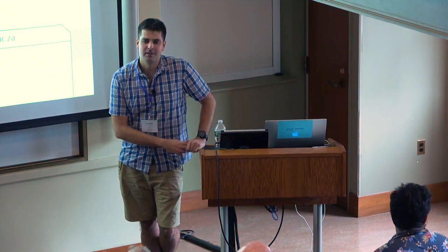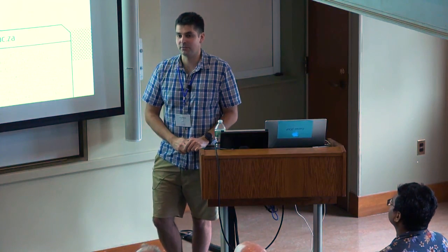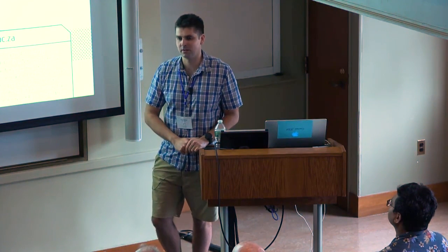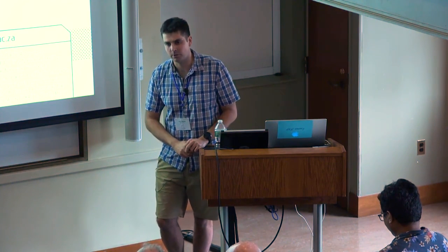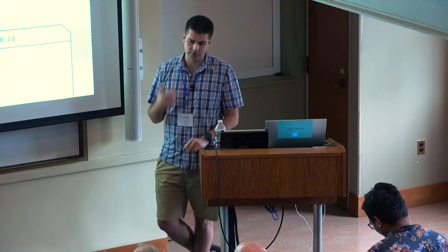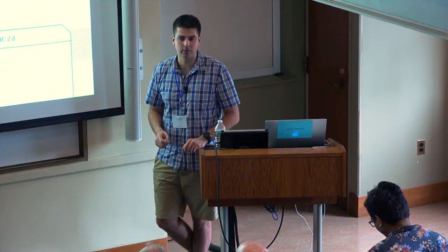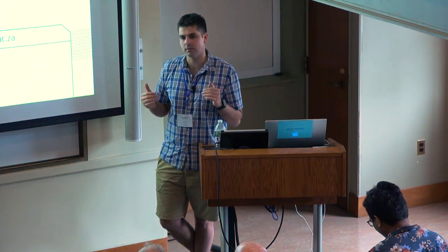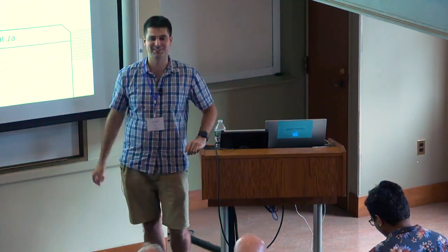So sometimes switches come with so-called deep buffers, and they cost like 3 or 4 times the open switch prices. So the question is, switches sometimes come with deep buffers, and I'm going to address this on Friday. I had a whole section on this, but we've run out of time today. That is actually critical. If you have PCs connected to the network, you really do want those deeper buffers, and it's worth paying the money for that. If you're just an FPGA system, you can get by with much cheaper switches. That's actually what we have on MeerKAT, with very shallow buffers, because you can coordinate the FPGAs' transmission of packets to sort of skew them. I don't want to get into too much, but look out for Friday's talk.